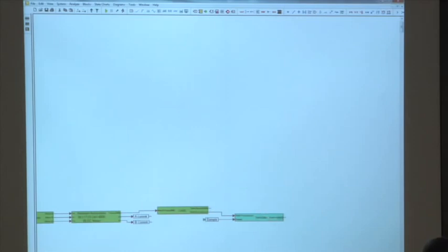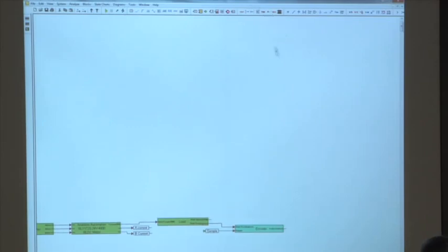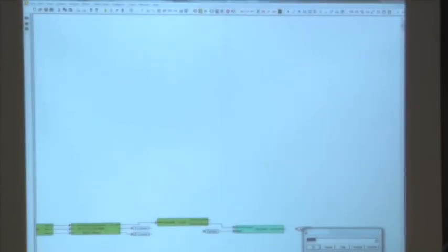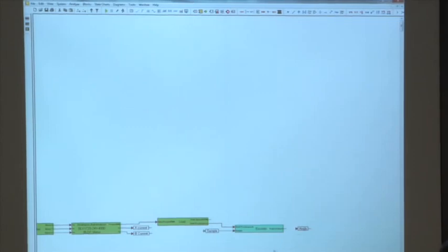Take the angle output of the encoder module, go up to the VAR tool again, and drag down a variable for the output of that. And we're going to change that, instead of variable, we're going to call it angle. And then connect that to the output block of the encoder.